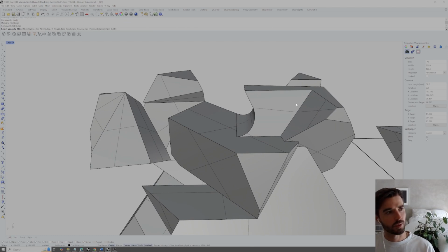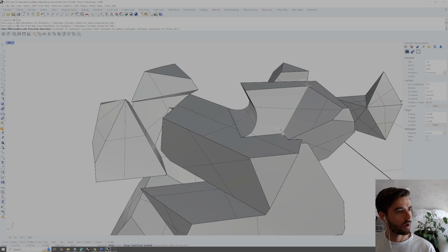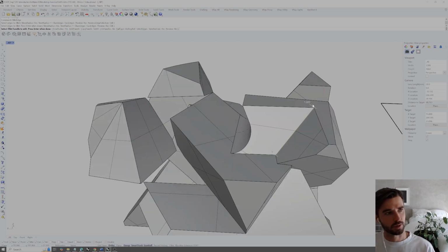We can also do a variable radius fillet, just with the Fillet Edge command again, but what we want to do is click, hit enter. When it shows us this preview, we can click on the end of either of these fillet radii. So first I'll click here. I'll actually leave that one at 1. I think that was a good size, but this top one could probably be much larger, let's say even 4.